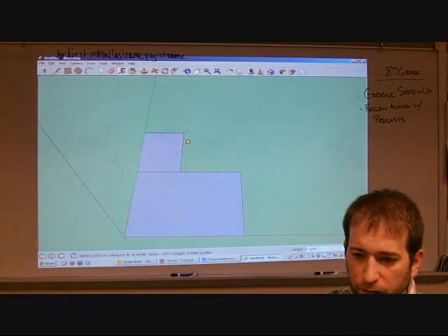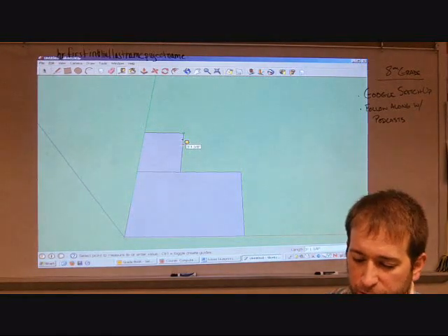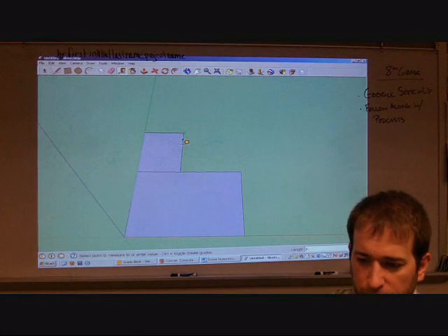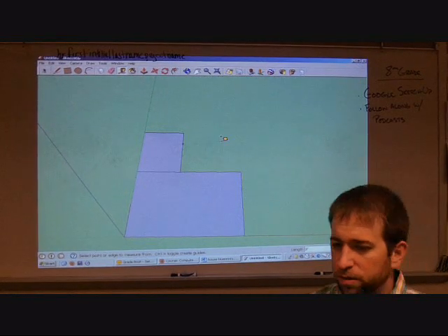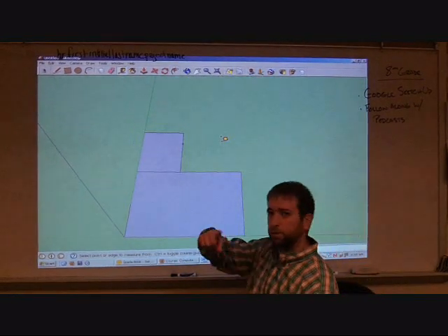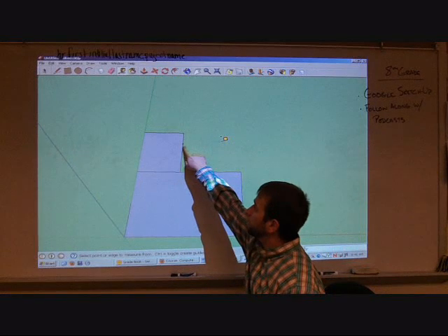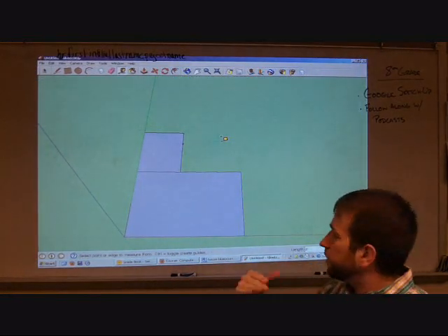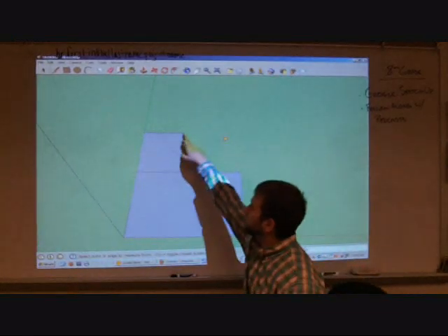So if I want to start out a room, I'm going to do my closet next. I'm going to start at 3 feet down from the top. So I'm going to just type 3 feet. And you can barely see, if you're on your computer, you can see a little better. There's a little tiny dot right there that represents 3 feet down from this top corner.